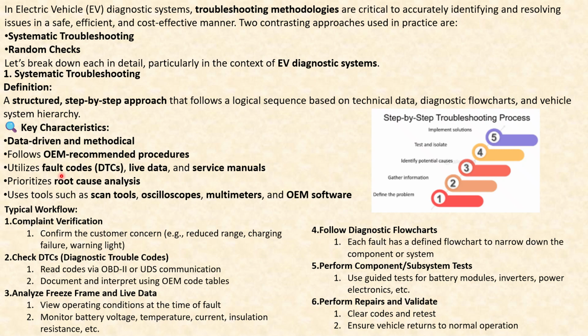It utilizes the fault codes, live data, and service manual. It prioritizes root cause analysis. It uses tools such as scan tools, oscilloscopes, multimeters, and OEM software. Now, let's touch upon the typical workflow.